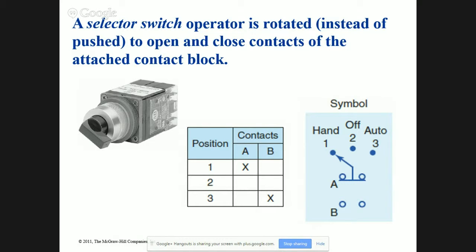Anybody seen some of the old control systems before touchscreens or human machine interface? The amount of buttons on it, there'd be like 100 buttons on the panel. You'd have to pay somebody to wire it, knock all the holes in, or you can put a nice clean little 10-inch hole and stick a touchscreen in there. If you're worried about the touchscreen going out, put 2 touchscreens on it. Or, like everybody else, buy a spare touchscreen and put it into stock. All you gotta do is load a program that'll work anywhere in the plant. Standardized.